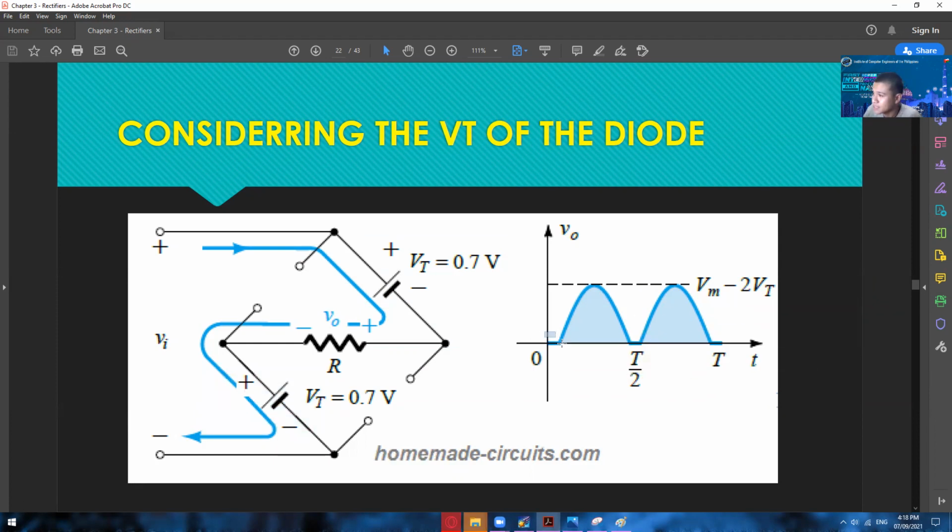And as you guys can see, our graph is now considering the voltage threshold. So for the first cycle, we have a deduction of 0.7. It won't permit a current unless you are able to give it enough voltage. So at exactly 0.8, that's the only time that it will permit a current. The same with the negative part. It will consume first the negative 0.7 before it will conduct a current.